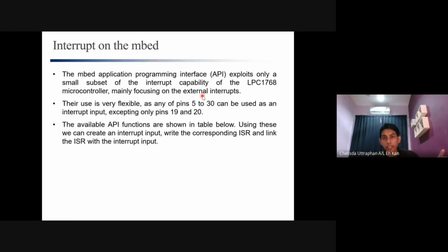For example, when you read the analog input, you ask the microcontroller to convert that analog input to digital. That takes time. When the process is finished, the microcontroller gives one interrupt signal to tell the microcontroller that yes, the conversion is finished and the data is ready.